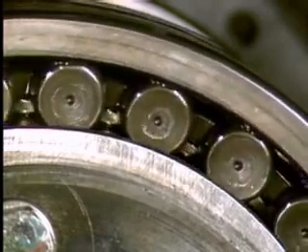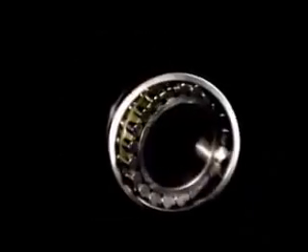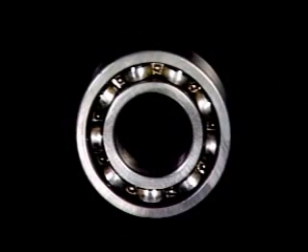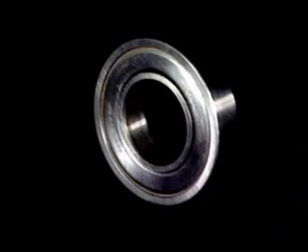Rolling element bearings, sometimes called anti-friction bearings, use rolling elements to help reduce friction. The rolling elements can be balls, cylinders, barrel-shaped rollers, or tapered rollers. In most rolling element bearings, the rolling elements are held in place between an inner ring and an outer ring. A metal retainer or cage often holds the balls in position and keeps them from rubbing against each other. Many rolling element bearings have a metal shield on one side, or sometimes on both sides. The shield helps keep lubricant in and dirt out.